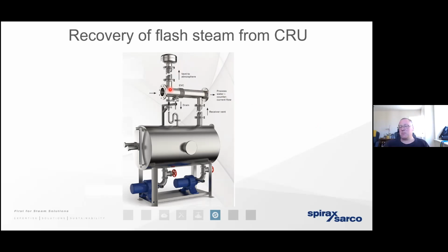And you may say, well, why is that important to the process? It's important because if we can get more and more hot condensate back to the hot well, not only is that condensate hot water, it's also chemically conditioned. It's in an ideal state for going back into the boiler. The fewer chemicals we're consuming, the lower the TDS level we're keeping in the boiler, the less blowdown we're performing. So we're getting less TDS, less foam being dragged out into the distribution pipework. We're getting less wet steam. We're helping to keep the steam as dry and free from particulate as we possibly can.